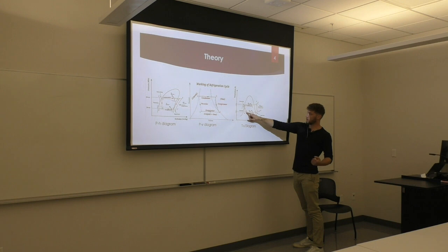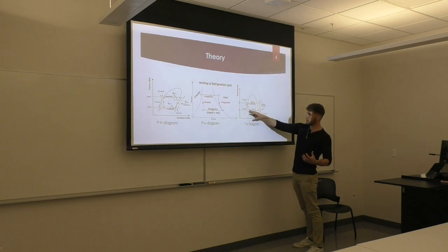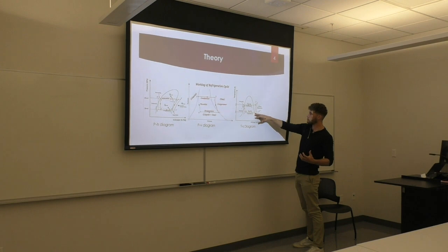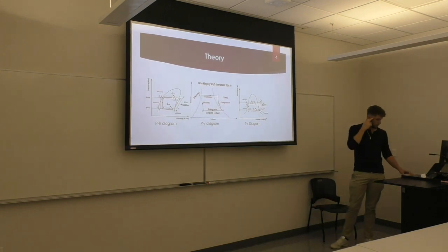Very cold, and it wants to pull heat from wherever it is around it as a saturated mixture. So you go through your evaporator, and it's pulling heat in, AKA cooling your surroundings as it's moving back towards superheated, and then the whole loop repeats. We know this, but just think about those states when we move forward.